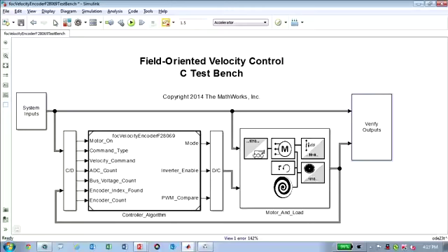Now, historically, Simulink would always be talking to variables in the MATLAB workspace. Was anybody ever frustrated when Simulink would talk to variables in the MATLAB workspace? They weren't. That's good. For those that might have been, one of the things that I heard a lot was we wish we had another container which was its own file that I could revision control that wasn't the MATLAB workspace. And that's where this data is in. It's in the data dictionary. And I can access the data dictionary using this icon in the lower left.